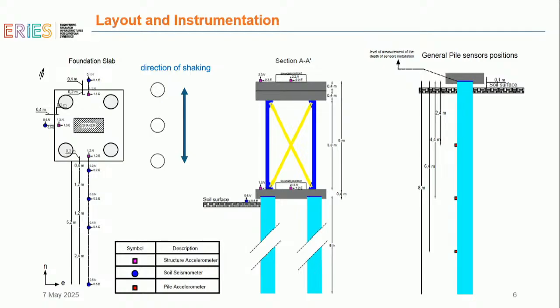We monitor during the test the response of the structure, so the roof up there. We monitor the response of the foundation. We monitor the response at the soil. You can see here the deployment of our instrumentation in the soil. And also we have instruments placed inside the piles. These are accelerometers, placed inside the piles to record the vibration of the piles.